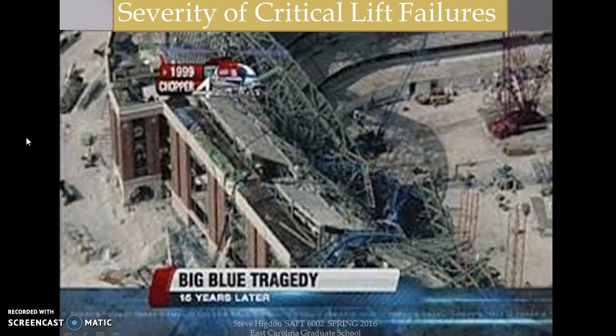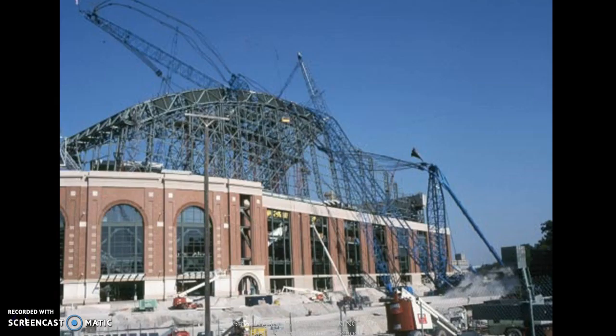The crane disaster that occurred in Milwaukee, Wisconsin on July 14, 1999 has come to be known as the Big Blue Crane Disaster. On this day, a critical lift rated at 97% of capacity failed. 3 iron workers were killed, and this was number 10 of the heavy lifts that have been completed on the site to date. Ironically, this crane disaster was filmed by an OSHA inspector who was on site investigating a minor infraction. The incident ended up costing 3 lives, $100 million in structural damage, $500,000 in fines, and $90 million in lawsuits. It was a totally avoidable incident.